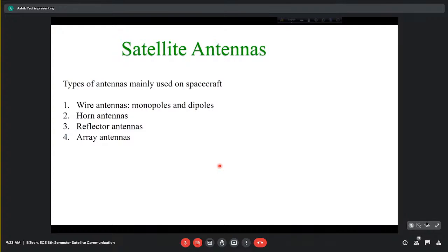Good. That means the surface of the antenna, which we see as a parabolic reflecting surface, only acts as a reflector of the incident electromagnetic, radio signal. That is concentrated towards the focus after reflection, and it is at this location that the LNA should be placed so that it receives the maximum amount of reflection from the surface of the antenna. There will be some losses, of course; not 100% of the incident energy is reflected back. But still, the LNA should be placed at the focus of the parabola, and it converts the incoming electromagnetic energy to electrical energy which drives current and produces voltage through that coaxial cable.